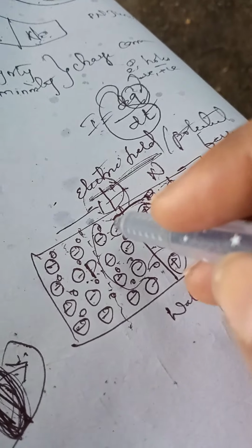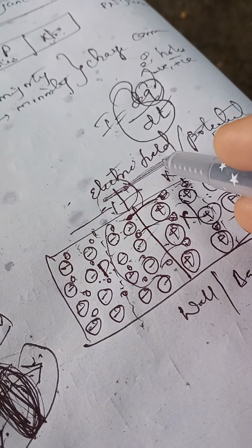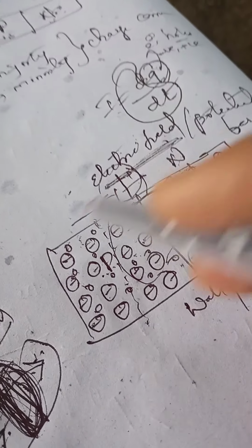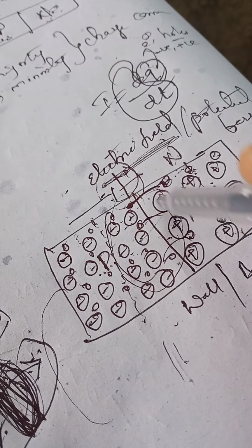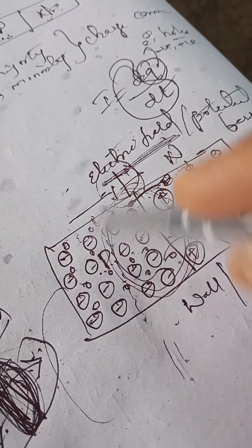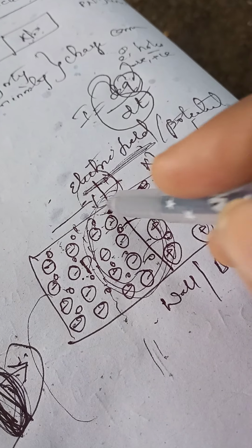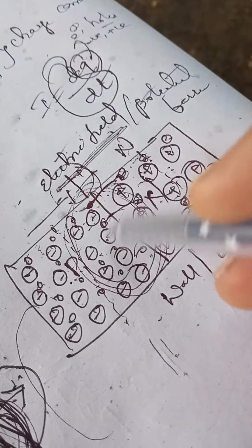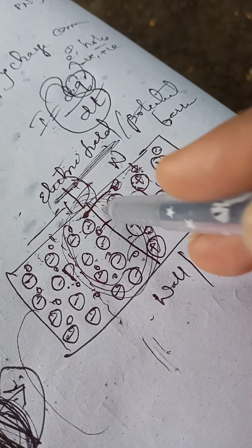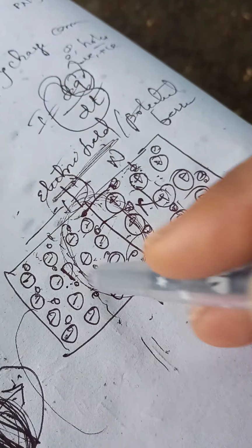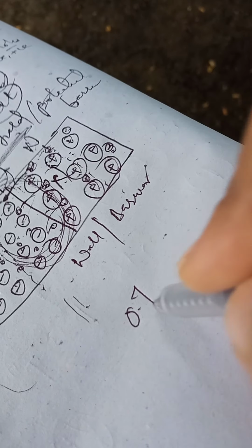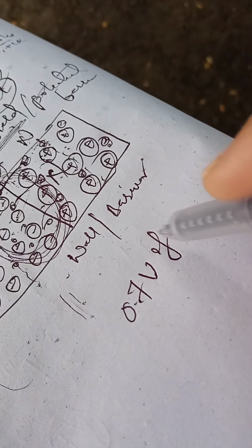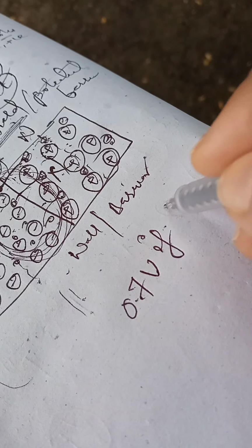Similarly here also, it forms an electric field or electric potential near the junction. So we have to apply an external potential that must be greater than the potential of this barrier. Then what is the potential offered by this depletion region, or the electric field established near the junction? It is 0.7 volts if the particular PN junction diode is made up of silicon,